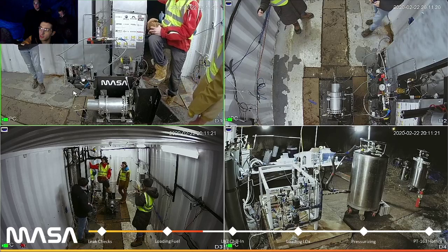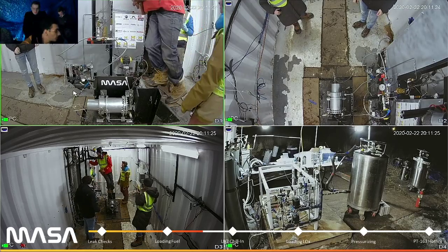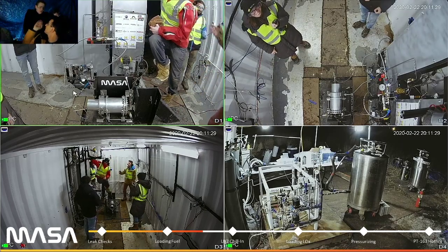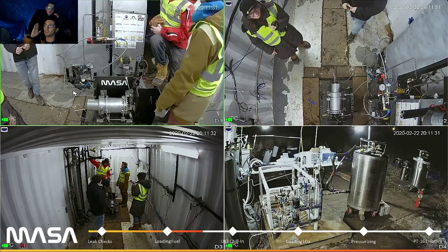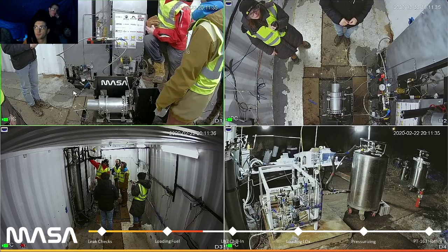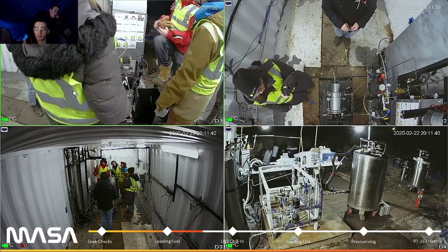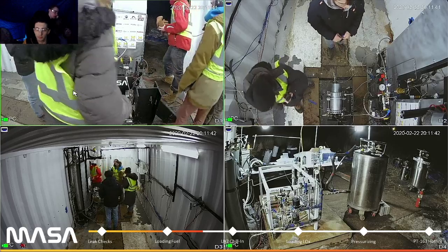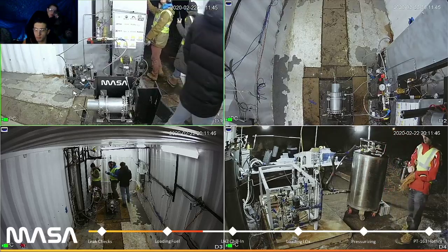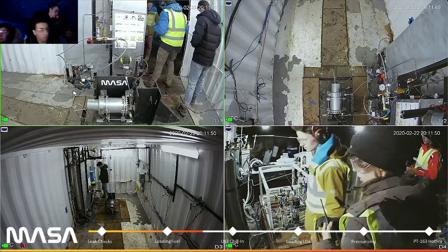So the injector is difficult to make. The orifice size is on the order of around 50 thou diameter. This is our injector. For the new RPD2 engine, the largest we're gonna have is about 90 thou, but they're approximately like 50 thou. PT-163 is a little bit smaller, probably around 40 thou. But RPD2 is a much larger engine, so we step it up a little bit.